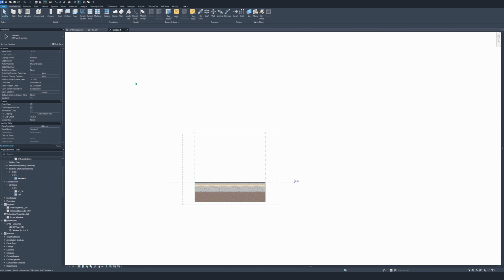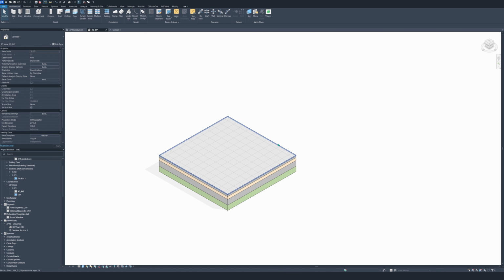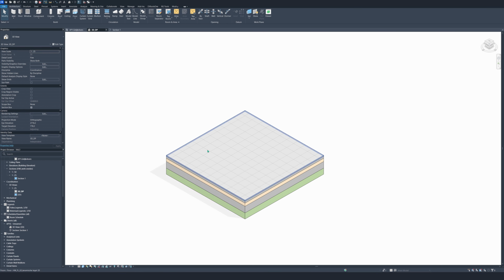So we're gonna check in 3D now. As you see, that's how we want it. And now we're gonna move the section box a little bit more inwards, so we are cutting through the material and see how it looks. Now mine is hidden. So to unhide it, we go to the lamp here, click on it, select the section box, and here unhide element, click on the lamp again, and voila, you have it.